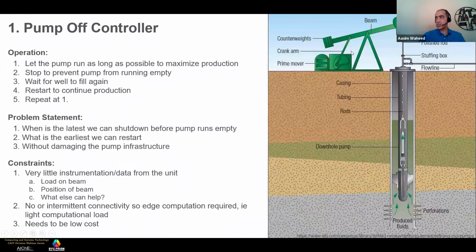So there's instrumentation up here that senses that it's running dry and stops the pump. Right now, it stops the pump for, let's say, an hour or a couple of hours, and waits for oil to flow back into the well from the reservoir and fill up a little bit. They assume that after X hours or X minutes it will be filled up again, and then they restart the pump.